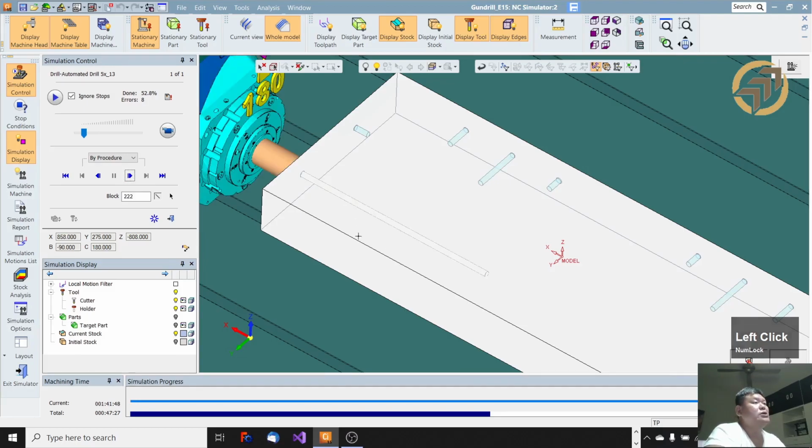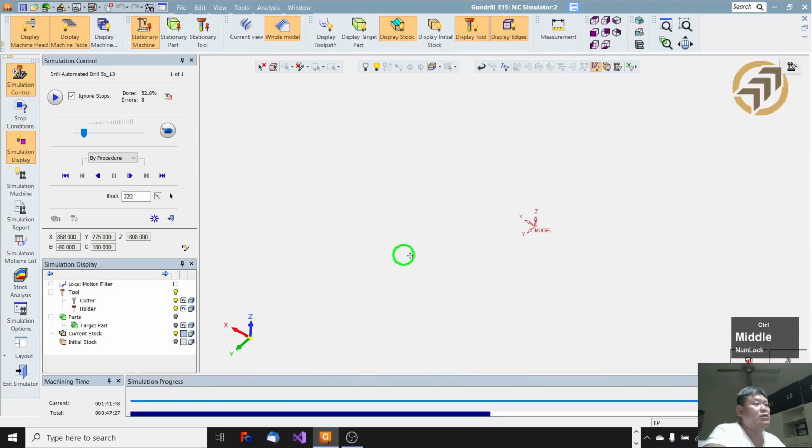Right. So after going down to the full depth, we can ask the tool to retract. For the next, it will retract 1 mm. And the tool will stay there for maybe 2 seconds, 3 seconds. This one all you can set.